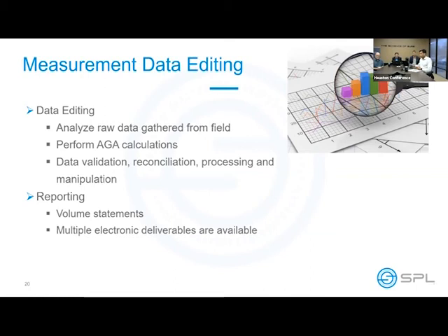You want to make sure that you've got good exceptions and good validation set into your system, so when something does go out of whack, and some of you are getting thousands and thousands of meters coming into your system with hourly data for each one, an analyst can't pick through that data and catch stuff. So you need a system that helps you to figure that out and determine where your issues might be so you can catch it up front instead of it making it all the way through your allocation process. And then that looks funky and you've got to rebook the whole thing because time is money.